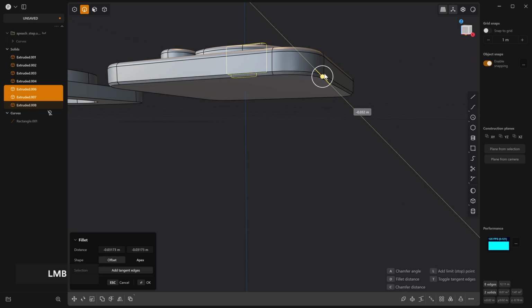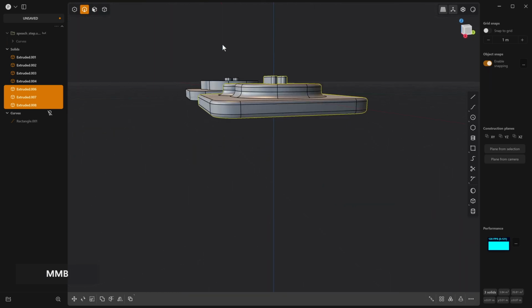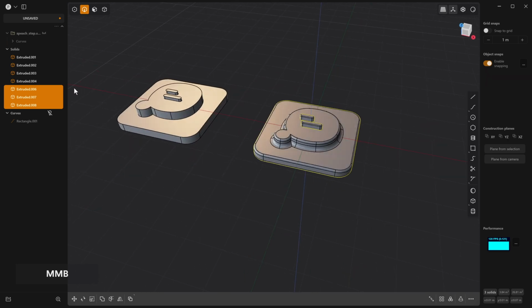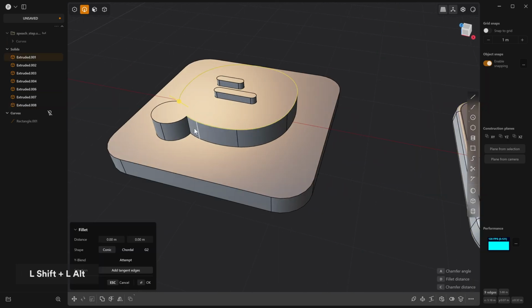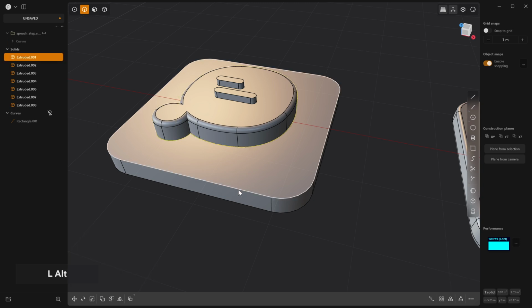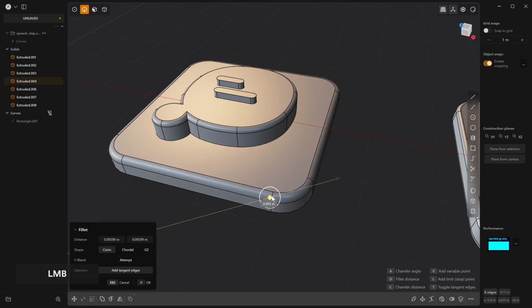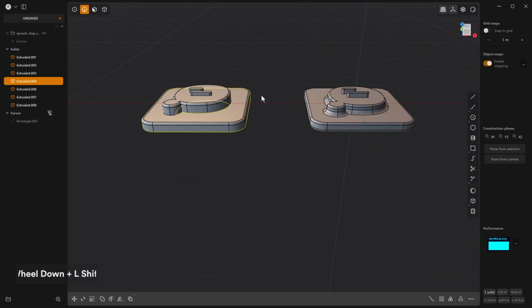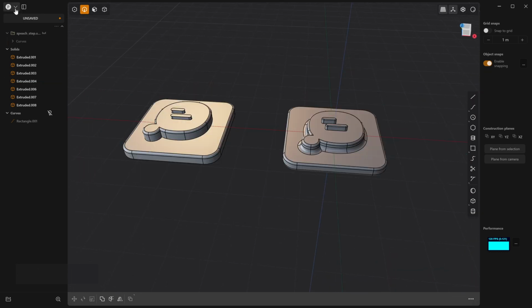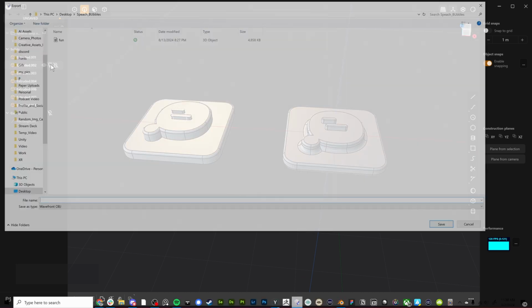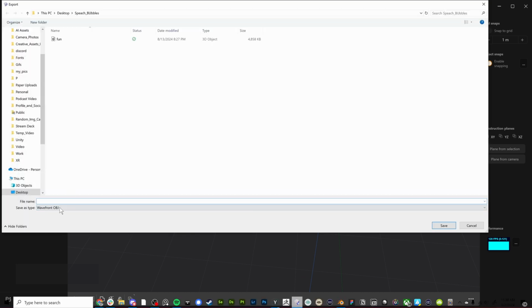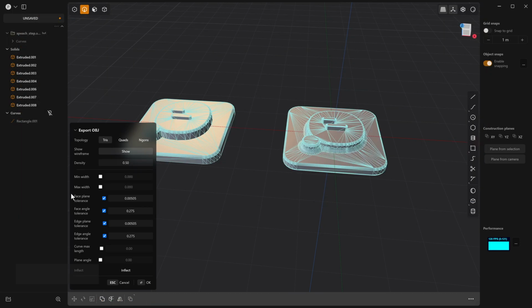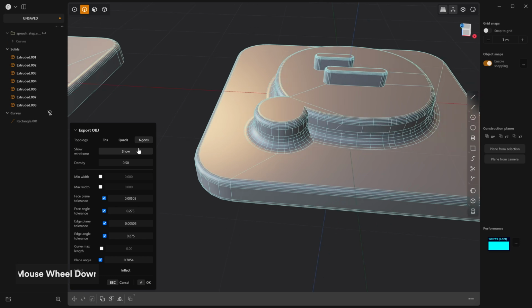But I'll show you some concepts at the end that I maybe spent 20 minutes to create and had a lot of fun with. So now that we have these created in Plasticity, let me actually just grab this and make this a little different so we can kind of tell when we bring it in from our other one. Cool. So now that I have these two in Plasticity, I can go into this export and basically save them as a wavefront OBJ. So if I just say file name, I don't know, fun, let's just say icon bubs. I can change these to n-gons and I can really play with the topology of this, right?